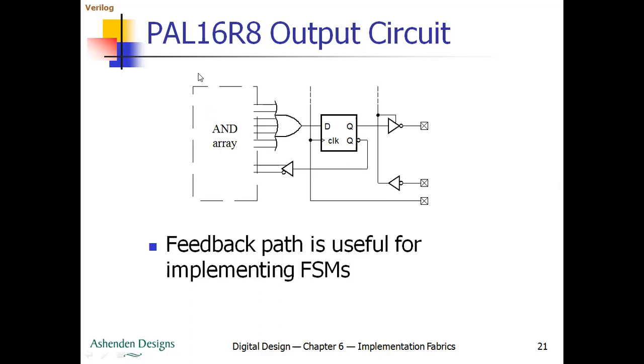Okay, like this. PAL16R8 is nothing but a variant, one more version, of PAL16L8. Here you can find the use of a register, a D flip-flop, which can be used as a register, and the output Q is connected to the tri-state buffer or driver. Using this register D, you can provide the feedback to the AND array.